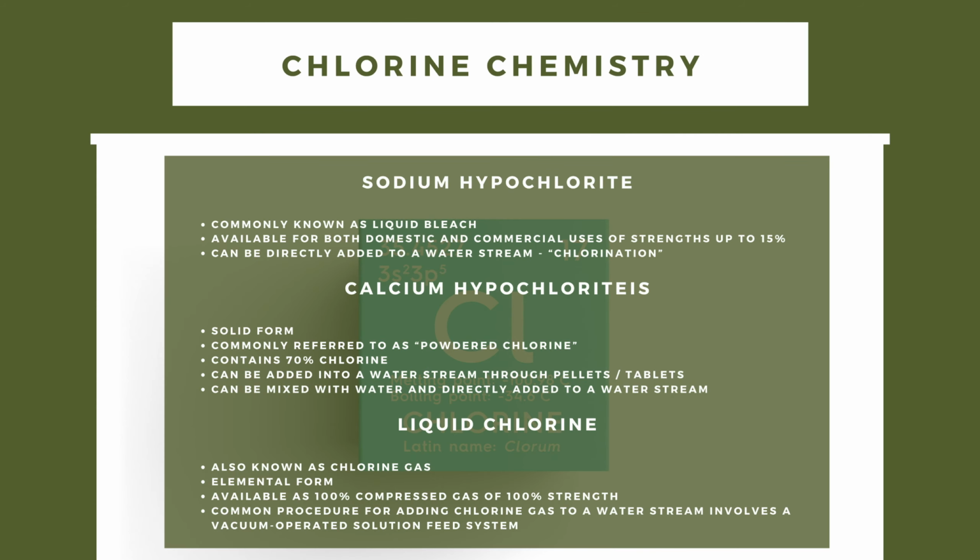Chlorine is a widely used, economical oxidizing agent that provides disinfection properties. Chlorine can be added to water in one of 3 forms: liquid, sodium hypochlorite; solid, calcium hypochlorite; and gas, liquid chlorine. Chlorine kills bacteria by attacking the cell membranes. Hypochlorous acid enters the cell wall with water and breaks down the enzymes in the cell wall. Chlorous acid is more of a tiny hammer to bacteria.